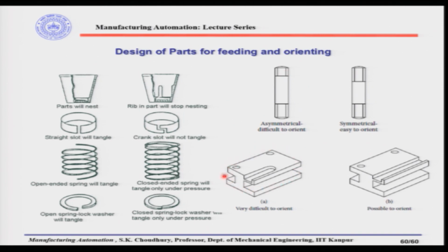Here there is a part shown which actually is very difficult to orient because of this groove here. So, this groove, since it is made not completely, let us say halfway or something, this is the design. So, this feature makes it very difficult to orient the parts. Suppose if we make it like this, in this case the functioning should not be affected, that is one thing. So, I repeat once again, any feature that we are introducing will be non-functional, in the sense that it should not disturb the functioning of that particular part.